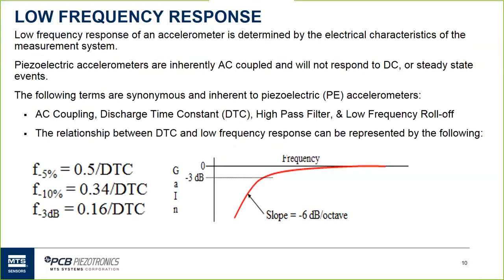And discharge time constant relates to the rate that the signal discharges back towards zero. Characteristic of piezoelectric sensors, they're going to respond to mechanical stimulus, and when the constant acceleration is experienced, their output decays back towards zero.